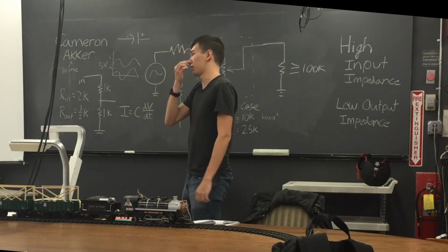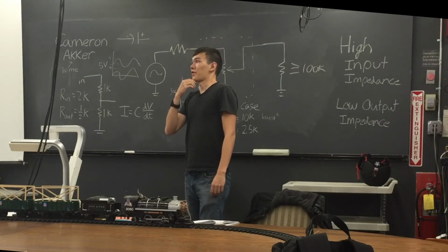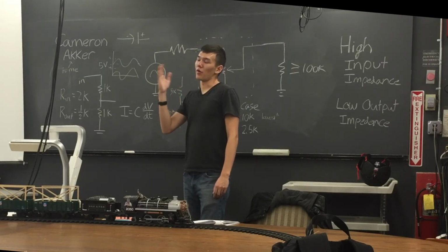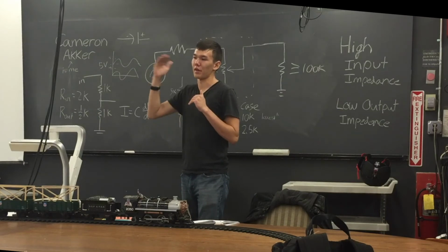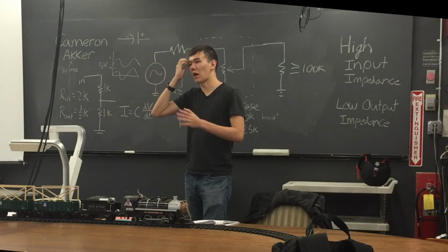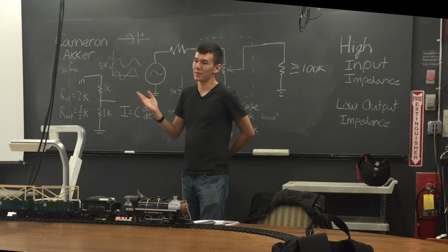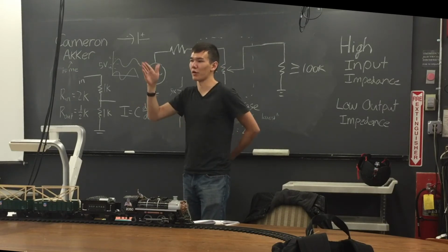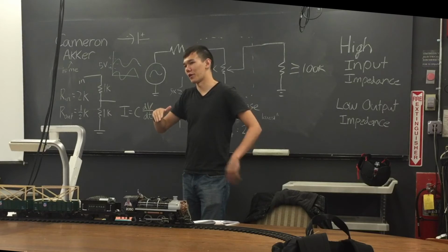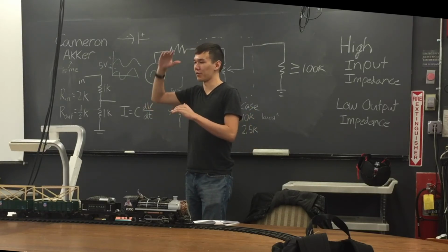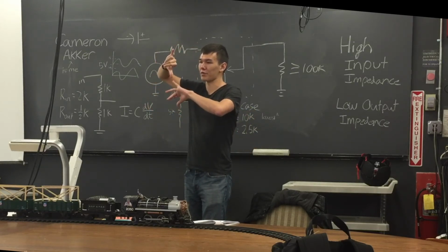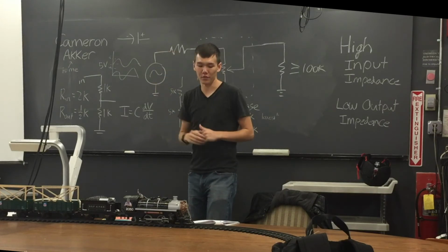So say there's a thermostat that, depending on what value you give it between 0 volts and 5 volts, it decides how hot it's going to blow the air. And you have a signal coming in that's somewhere between, you know, +1 and -1 volts. Oh, okay. So you want to amplify it up until 2.5 on either side, and then you want to shift it up 2.5. Okay, that makes sense.